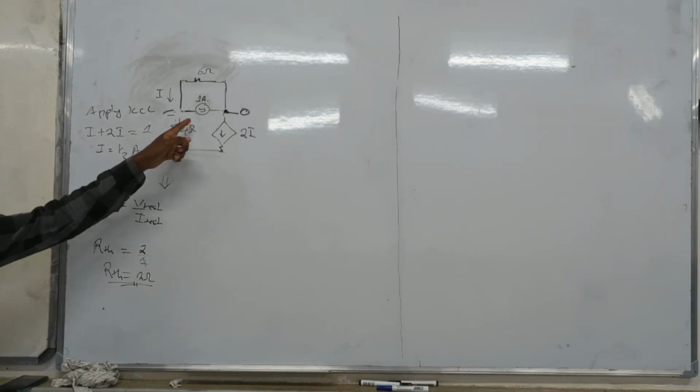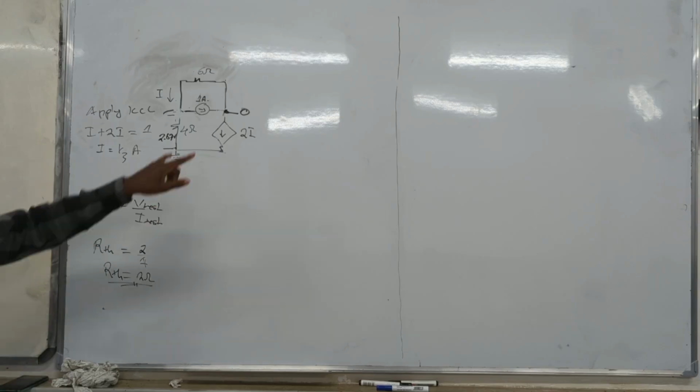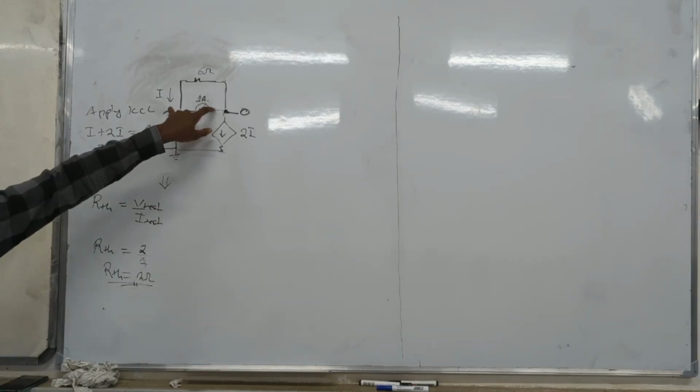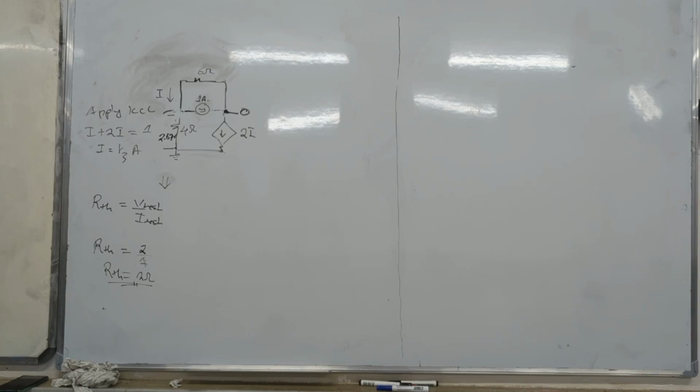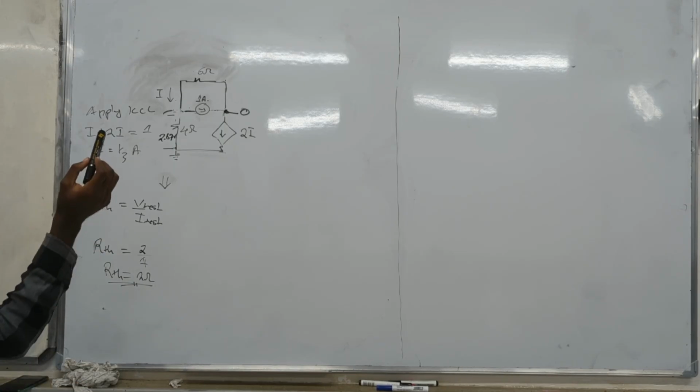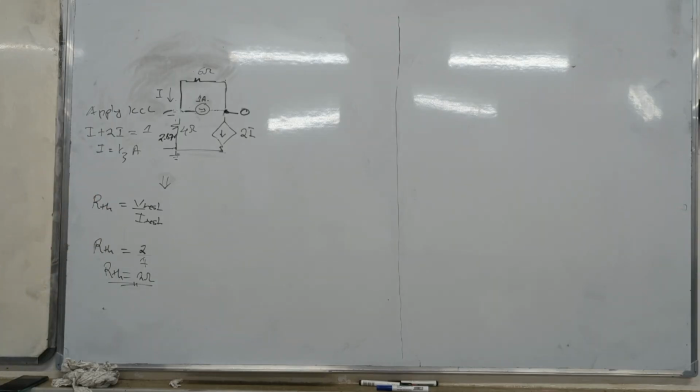Okay. So we want to get the voltage between these 2 points. The easiest way of getting the voltage, you set one terminal at 0, or one point of interest. Then you move from that point, applying KVL, to the other point.